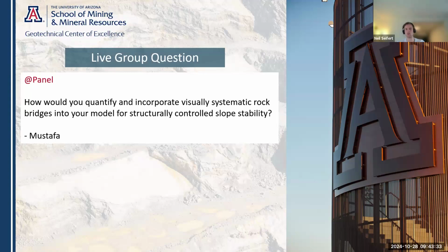I think a note of caution too. If you're in the first couple of benches of your mine and you're seeing these rock bridges, depending, of course, how wide they are, as your mine progresses and as you continue blasting and excavating that rock mass, I think it's really important to keep monitoring those, because there is potential that through continued blasting you might actually connect these, and then they cause more instability than they did at the first few benches. Of course, this is a scale thing. If your rock bridges are super far apart, then that might not happen.